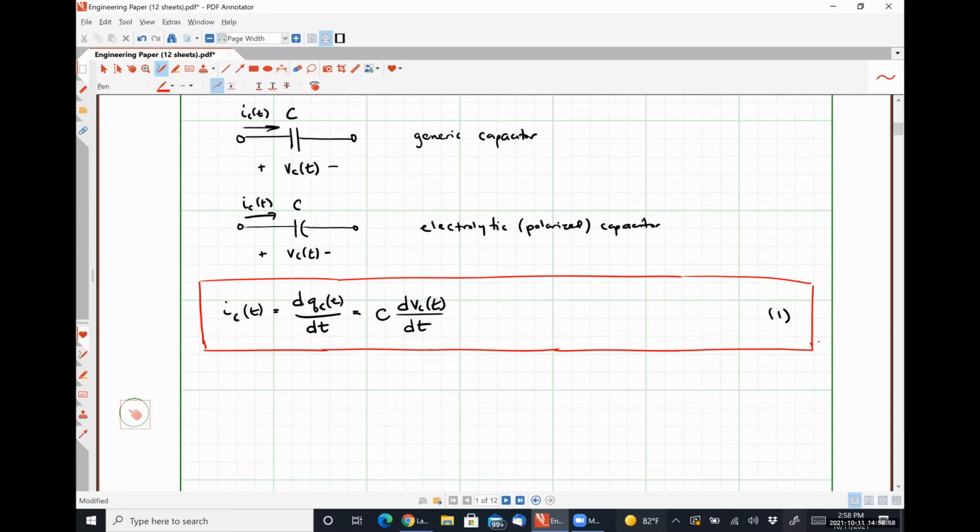Literally, every single one of them is going to show up again where the voltage and current are switched, and we replace all of our L's for inductance with C for capacitance. They are that closely related. They're called electrical duals, okay? So they have the exact same characteristics, except that current and voltage are interchanged.